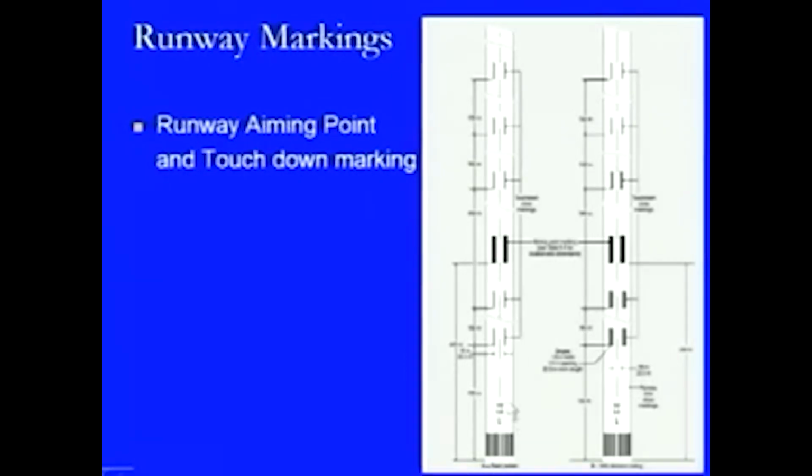So, this is a runway number marking which is 20 L, meaning L for left, and 20 defines the angle at which this runway strip is provided with respect to the overall angle of space, that is 360 degrees. So, it is 200 degrees in this case, and then this is the center line being shown in this basic diagram, and along with that we have the touchdown zone markings shown as a single strip on both sides, and it keeps on going up to this distance. So, this becomes the touchdown zone.